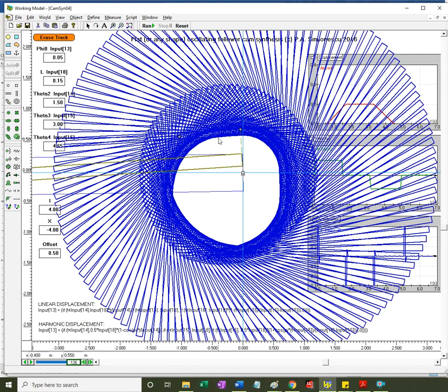Yes, so if you see straight portions on the cam profile resulting from the envelope, that's a sign of the undercut. Because if I'm to cut this cam disc out of stock and have it operate with the follower, when the flat face of the follower engages this portion of the cam, it makes contact here and then jumps to a contact here.